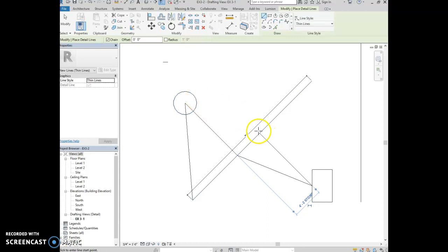Then I'm going to go from here to a tangent. And let's see if we can find the shortcut for tangent, ST. So I'm going to type ST, and that lets me click on that tangent. And I'm going to click from the tangent.